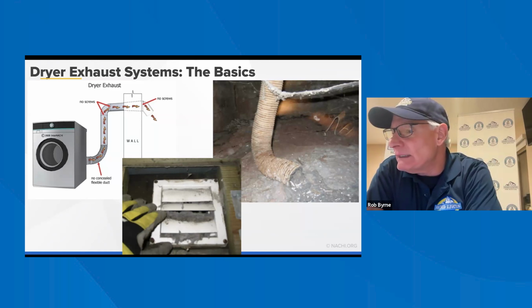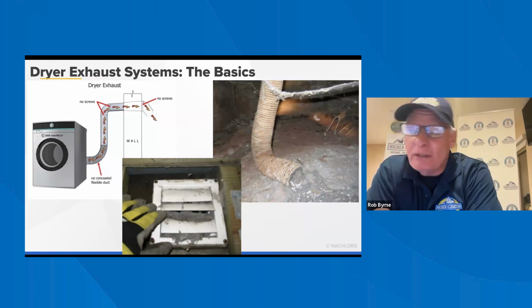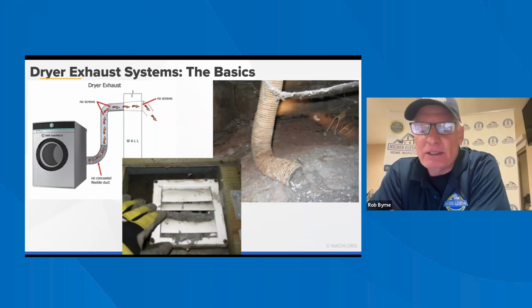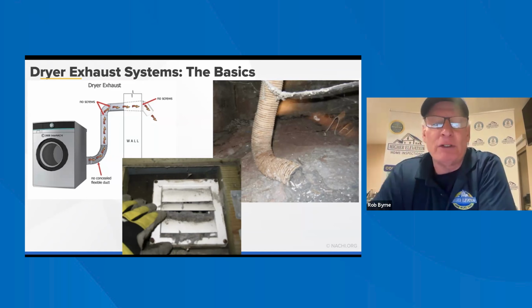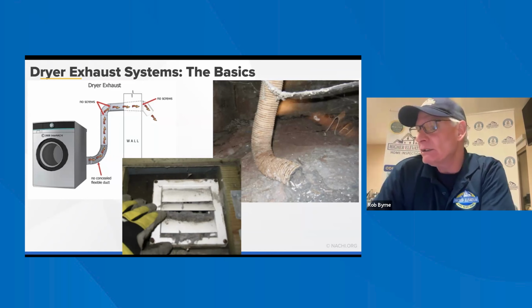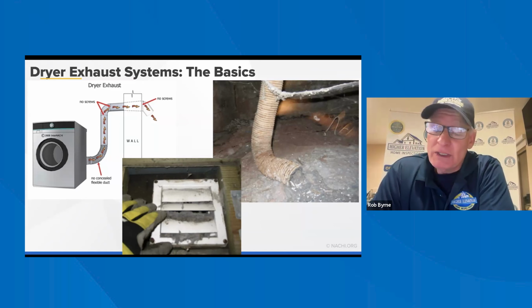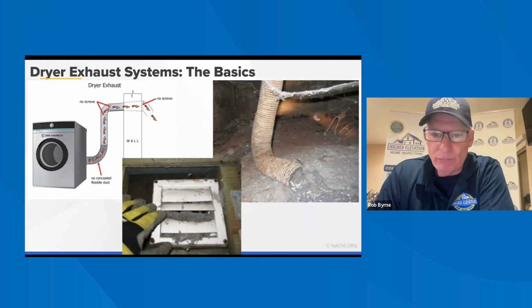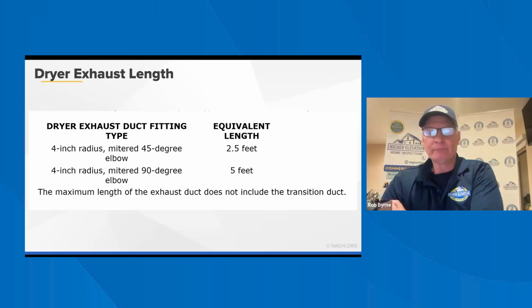Closed dryer vents emit exhaust air that is laden with moisture and lint. So that's a good point too. Not only is the lint flammable, you're putting moisture back into the living space, which you don't want. So all the dryer vents should exhaust to the outside. They must be discharged outside. You'll also see this in attics. Sometimes they discharge them into the attic if the dryer's up on the second floor and you've got the attic above you. You don't want to do that. Not a good idea.